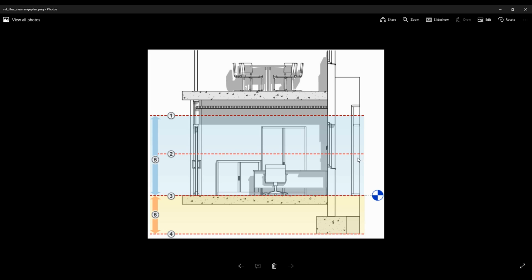this right here is your cut plane. So this is the area from where you'd be looking down if this is a plan view. The reflected ceiling plans are a little bit different when it comes to view range, and it can be kind of confusing because they're kind of backwards. But this picture here applies to plan views. So yeah, this is the area where you're looking down, and you'll get all elements between here and here showing up, and the cut pattern will be right on this line.